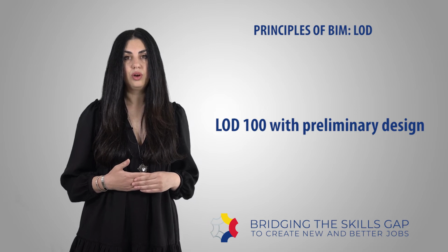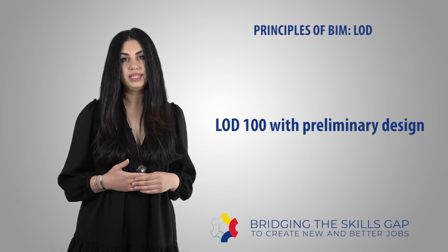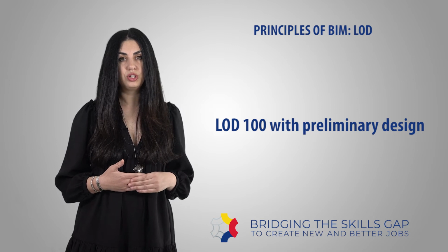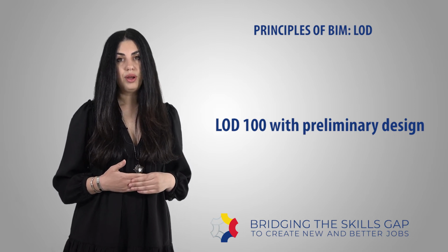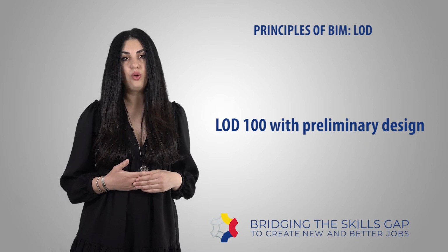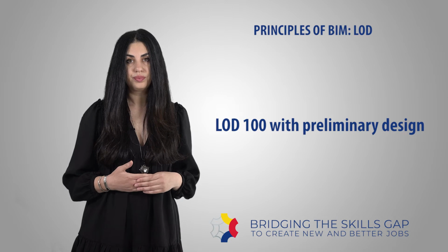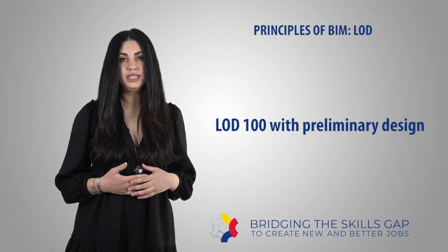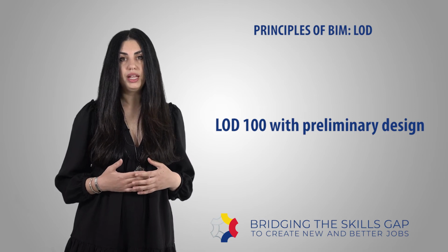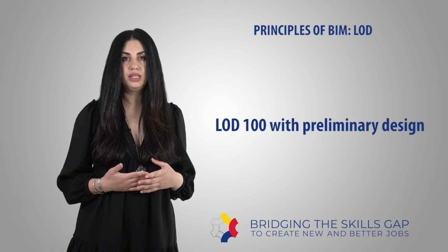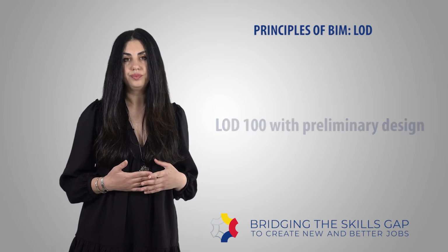LOD 100 is a concept design. The building 3D model is developed to represent the information on a basic level. Thereby, only conceptual model creation is possible in this stage. Parameters like area, height, volume, location, and orientation are defined. Let's take a look at this column. LOD 100 is a basic overall idea of the shape and no data. Just a box which may be graphically represented in the model with a symbol.